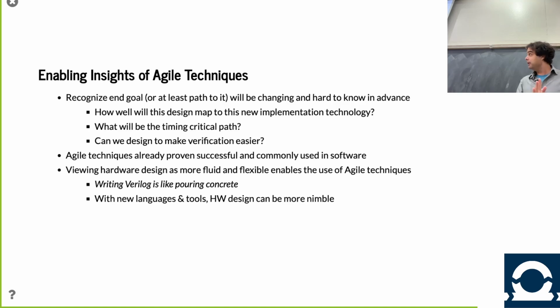And guess what? Concrete, if it's the right shape in the right place, will last a long time, right? It's concrete from the Romans. There was Verilog that's 30 years old that's still being used today, in chips we're using today, right? The problem is that once it's all there, it's really hard to modify. It's not just a matter of how brittle it is; you're also going to change your verification, the thing that allowed you to verify that Verilog. Once you change that Verilog, you break the seal on that verification, and now you have to re-verify all of this. And so what's enabling agile design for hardware is actually new languages and new tools. With new languages and new tools, we're much more able to adapt and rerun things.